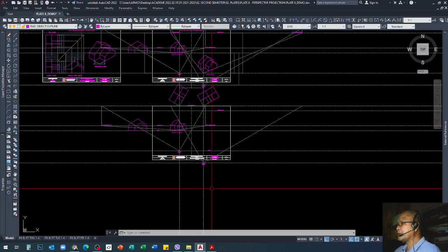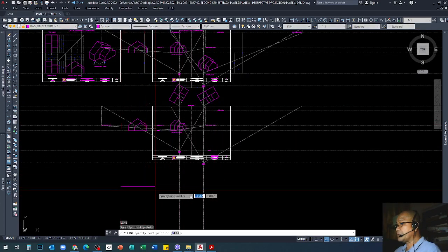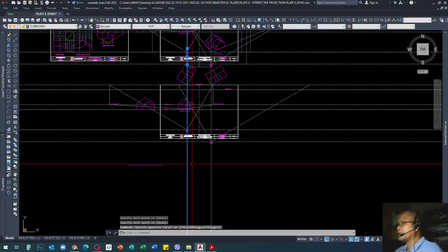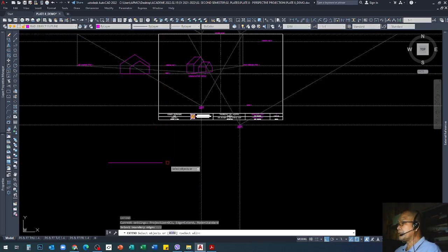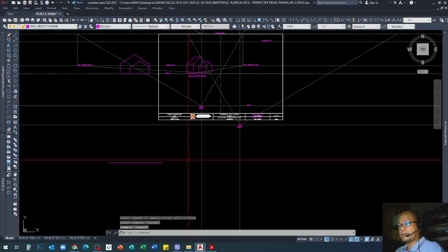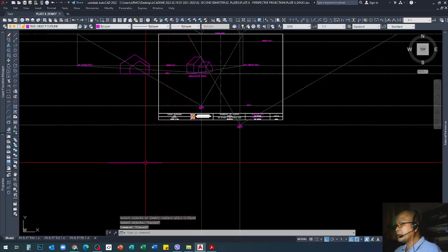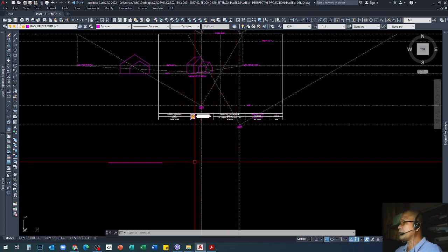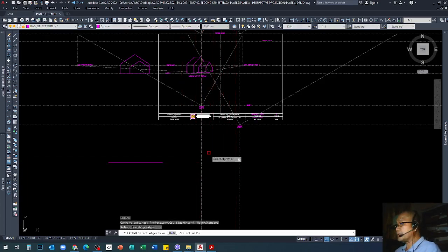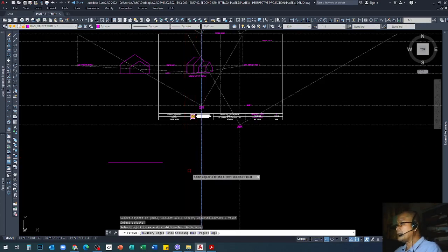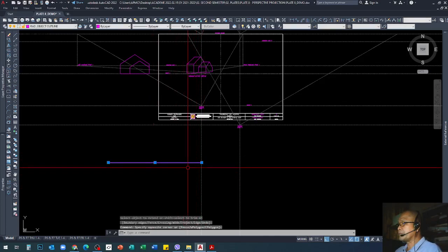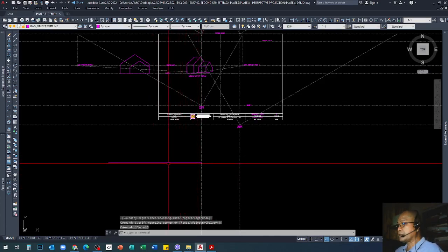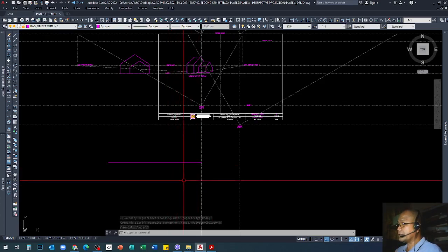In extend, for example this line, you need to extend up to here. Last time when I typed extend, if I trim, you can directly extend the line to here and then click again to here. But as I used to do it, I always click the object where I bring the other line or any object to that point. So for this, the option is to put it back to the old one.